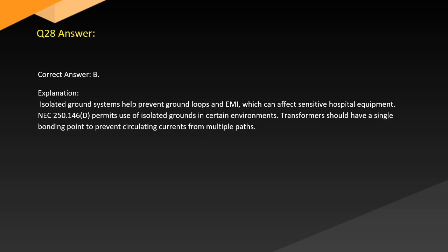Answer. Correct answer: B. Explanation. Isolated ground systems help prevent ground loops and EMI, which can affect sensitive hospital equipment. NEC 250.146(D) permits use of isolated grounds in certain environments. Transformers should have a single bonding point to prevent circulating currents from multiple paths.